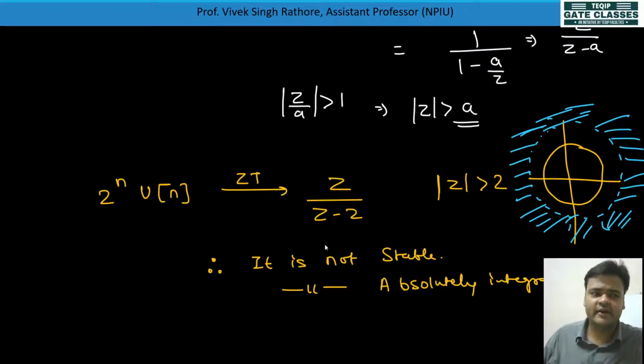And then you can tell that this signal will have a Fourier transform, because I told you that Fourier transform is a specific version of the more generalized transform, Laplace or Z. Z is in the discrete domain. So the discrete time Fourier transform, that is DTFT, is possible only when the signal is stable, absolutely integrable, or the ROC involves the r equal to 1 circle.